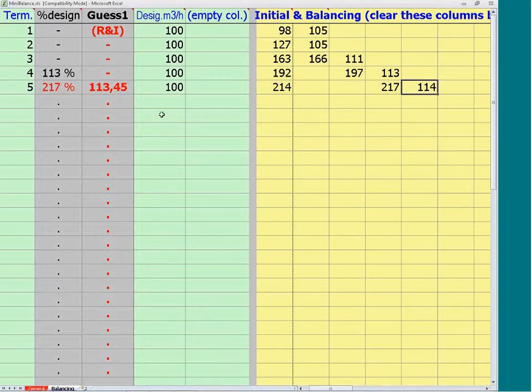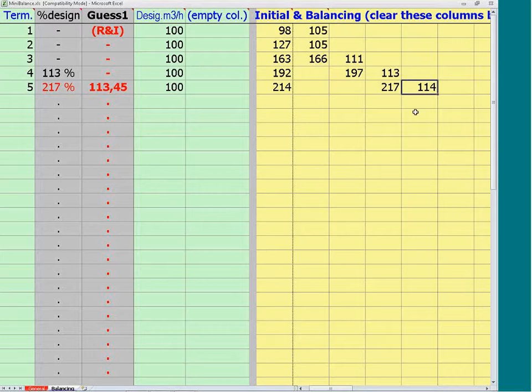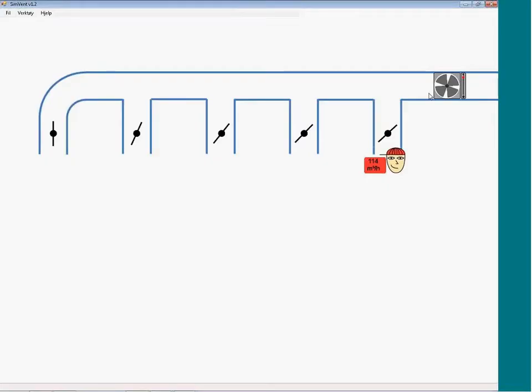Okay. If one wants to throttle it exactly to the value that the spreadsheet calculates, it doesn't matter. All you have to do is measure the value that you actually got and write the actual value that you got in the spreadsheet, even though it's different from what the spreadsheet recommends. Now, we throttle all the terminals. Shall we see what values you get for all of them?